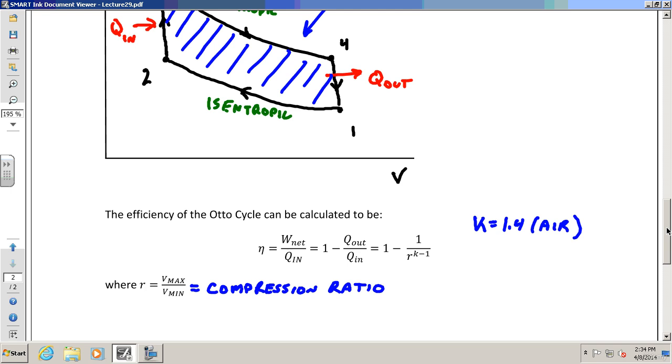You want to ignite when the spark plug goes, and that spark plug goes when you're at a minimum volume. But if it ignites too early, that puts a whole lot of pressure on those pistons. It hits it the wrong way. The engine's connecting rods and the rest of the assembly get a way different amount of force that they're not designed for.